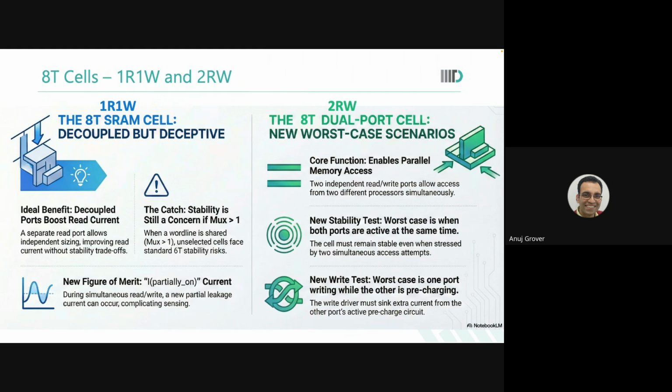Why not? It's much bigger. It is still bigger than the pass gate. But what will be required? A larger VDS because you are in the linear region. A larger VDS means larger Vx. So cell stability will go for a toss. Are you able to visualize this?